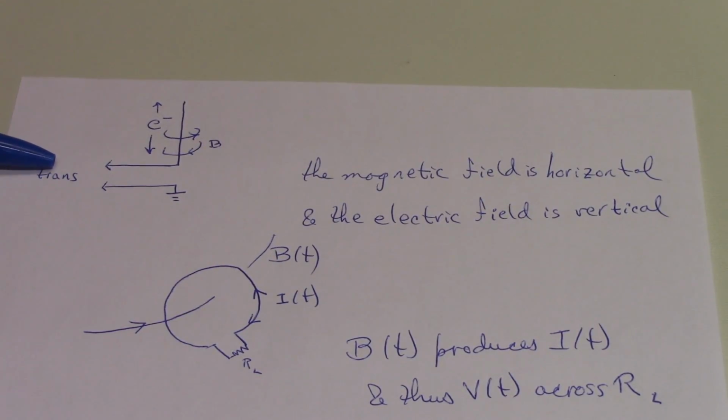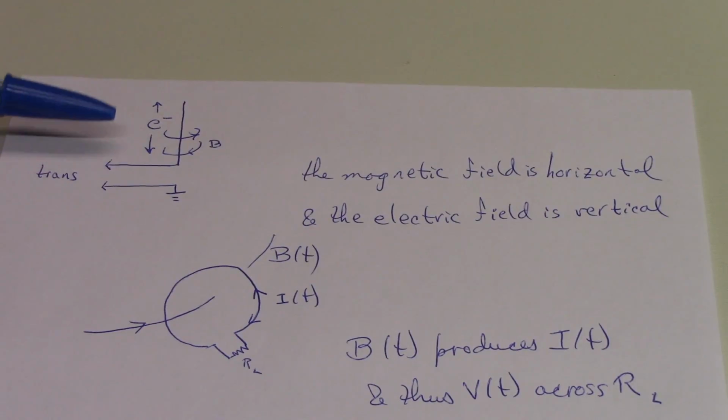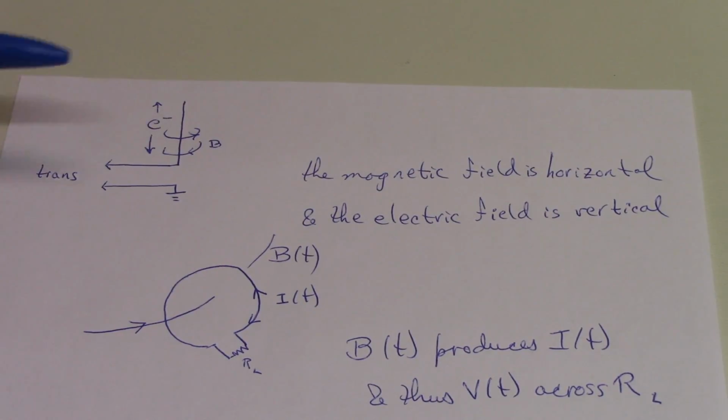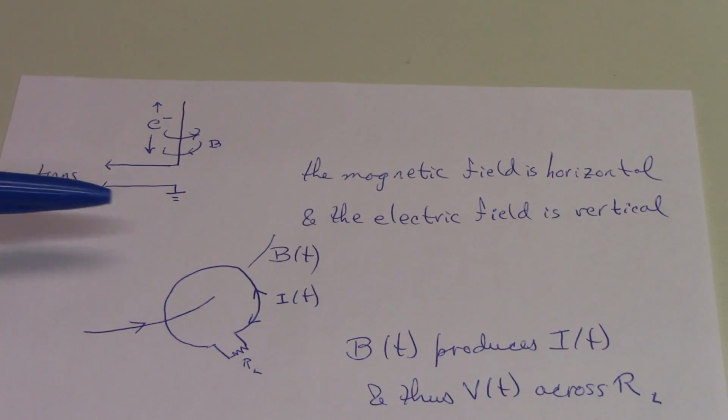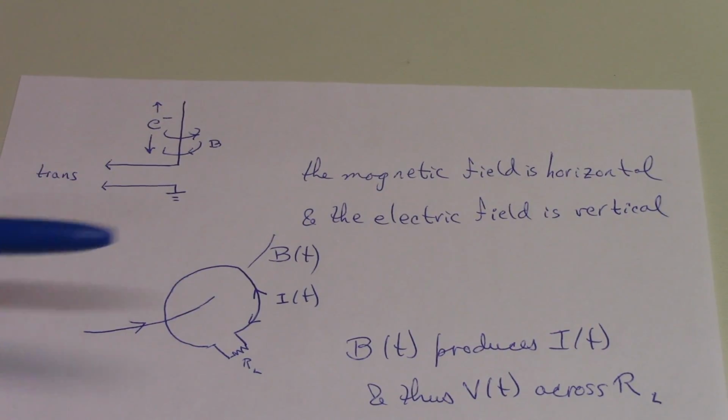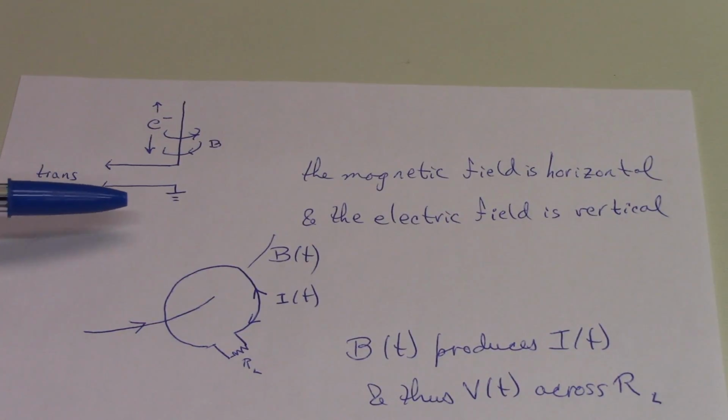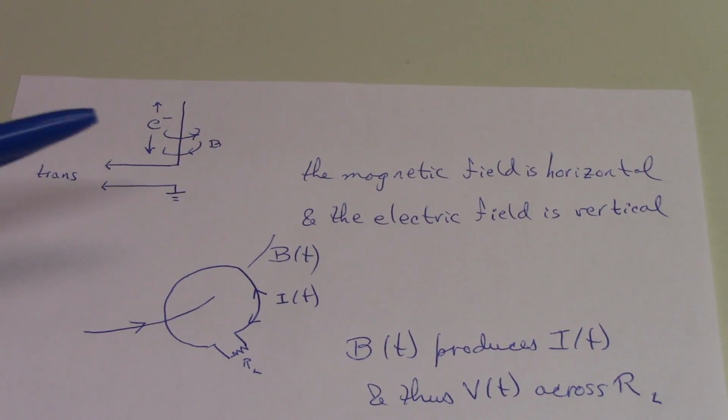You have a transmitter that delivers an RF voltage to an antenna that is generally a quarter of a wavelength high, or at least is electrically, and then grounded. And the conductivity of the ground, or the ground radials, is such that the second half of the dipole is completed by images down into the conductive earth.